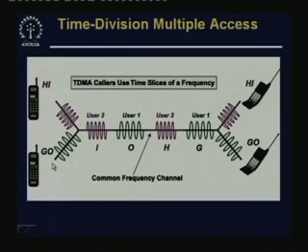So, immediately you see the problem. What happens if this nice synchronous behavior breaks down? Somehow you have to make sure that they do not break down and they do communicate at precise slots of time which is assigned to them, and then you have the additional trouble of ensuring that their clocks synchronize, because if he is running a clock of his own and he is running a clock of his own, these two clocks may not agree in real life. So, how to synchronize them, etc. These are the problems which you solve in TDMA, time division multiple access. Otherwise, the basic approach is the same as time division multiplexing.